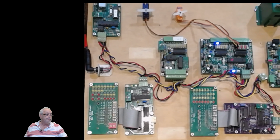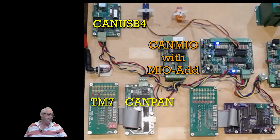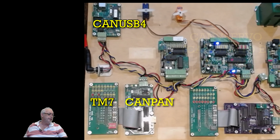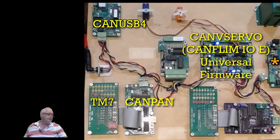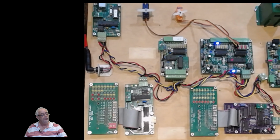So here we have the TM7 board with the LEDs and the switches. Over here we've got the CANPAN connected to it. Up here is our CAN USB 4. This board's not in use, it's a CANMIO. The board that's being used here is a CANVServo. And the board there is not even connected, so it won't appear in MMC. The other boards I've left disconnected as well for this example. So our scenario is going to exist on that board, and we'll be configuring using this one.